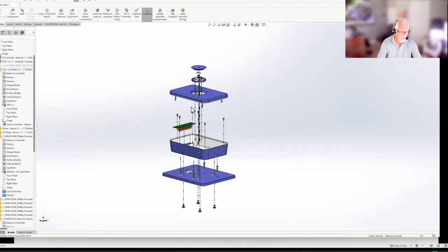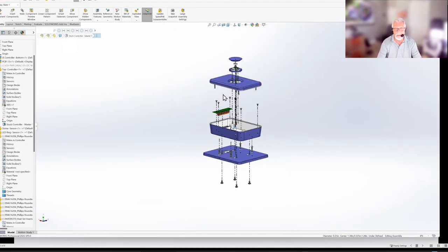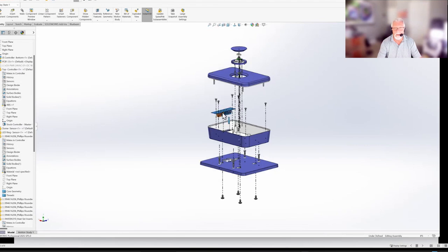Oh, I like this one. Hit the G key. Look what you find. This zooms in. I can zoom in a little bit more. Say I want to select that edge. Now that would have been impossible. Otherwise, I'd have to go in like this, right? Select that edge. Once again, hit the G key. And this is in anywhere you're at. This is your magnifying glass. And then you can zoom in, and then you can control what that zoom in is.